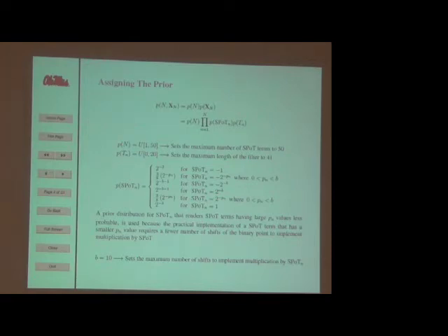And again, this is because if I can, I want to design this filter so that I don't have to do any more shifts of the values than I have to. This helps reduce the complexity of the filter by lowering the word size that's required to implement it. Although I do have a hard lower limit that I set to 10 in these examples.